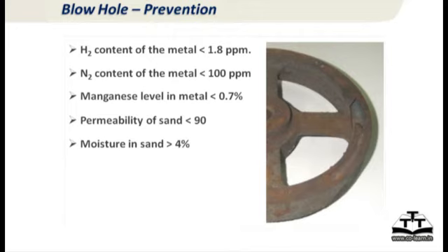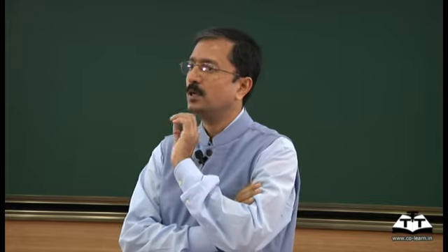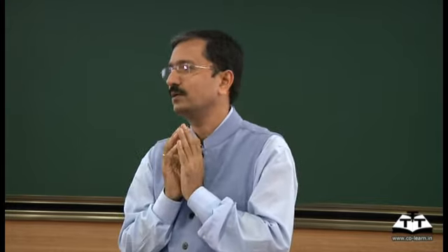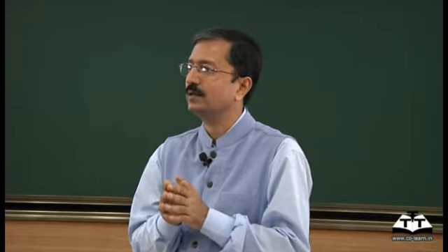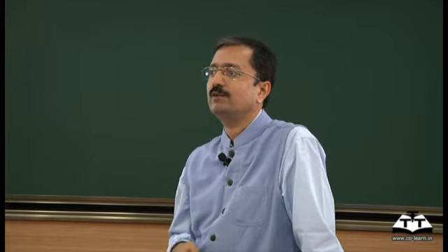It's a little more complicated than that. Manganese will affect your solidification characteristics, and therefore you are allowing the gas to escape a little better and things like that. But it is a little complicated, that even we don't understand. We know experimentally that if you keep the manganese less than 1%, it reduces blowholes. The mechanism of that is still not very well understood. We only know experimental values of that.